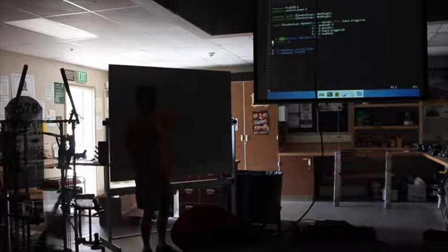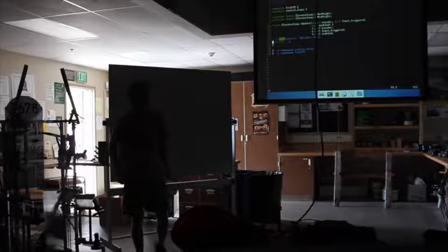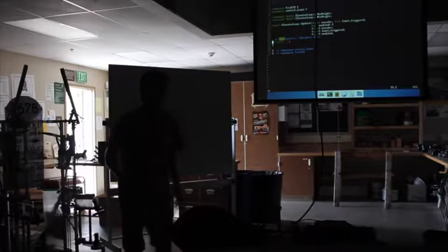So we're going to add some other checks in here too, like we're not going to let the driver request the elevator up here. We're not going to let it request it through the floor. A couple little checks like that, so we prevent him from doing that stuff so we don't break the robot, and that makes the software more robust. So it's a great question. Thank you. And just to clarify, all your control loops are running from the beginning. All that driver input does is change states or inputs. Let me show you my interface. Oh, I closed it.